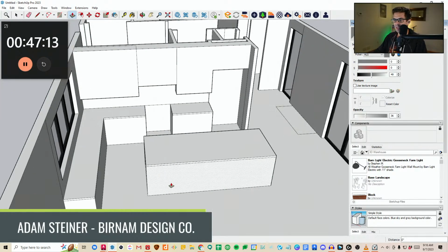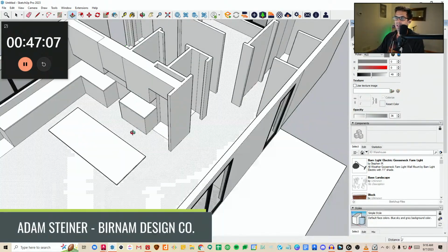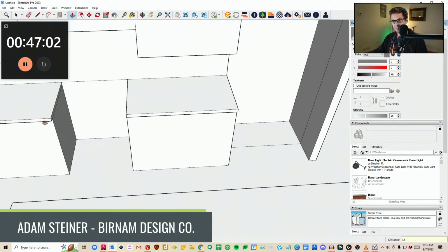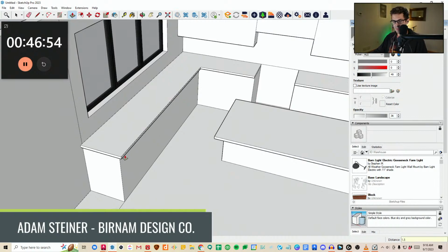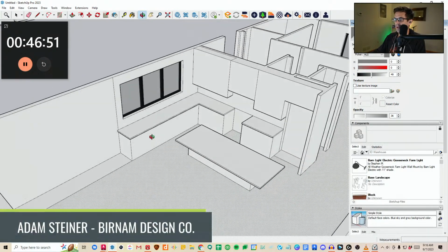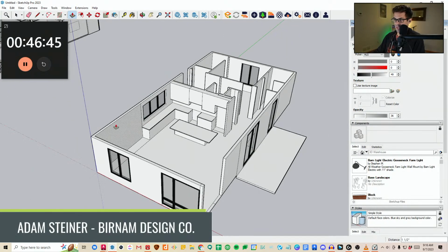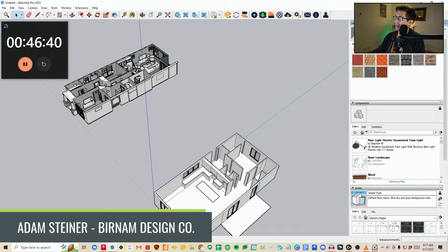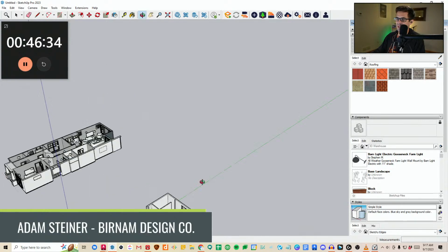And now let's do our overhang, which is 2 feet and 2 feet. Okay. And then now I'm going to bring all these out 1.5 inches so that it looks and feels a little bit more like a real countertop. So, countertop sticking over our ledge here. I'm leaving this line here because I want to use a tile backsplash there, which I can grab from our other model. So this is why I used it. I just have a nice normal subway tile backsplash.